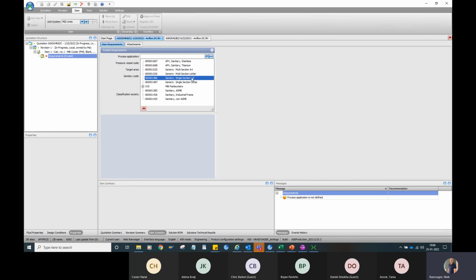If you select single, you will not have plate stamping included in your pricing. For food heat exchangers, which often are in multi-passes or multi-sections, we should always select multi-section, so we have numbers stamped into the plates, because they are a lot more difficult to rebuild or refurbish. So for the service guys, it is very important that we have a position number stamped in each plate, so they can easily find out where this plate has to sit. Does that make sense?